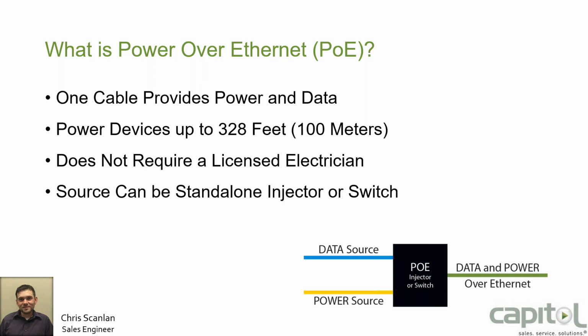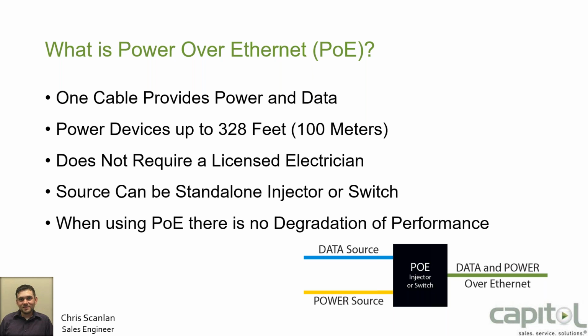The source can be a standalone PoE injector, as you see below, or a switch that has PoE built in. Some people have said in the past that if you're doing PoE, there's a degradation of performance. PoE does not degrade the signal. There's no degradation of performance if you're using PoE.